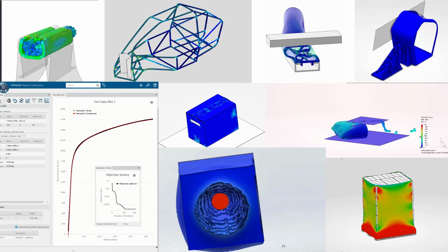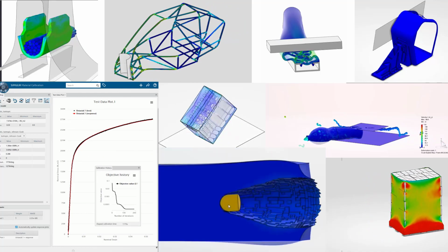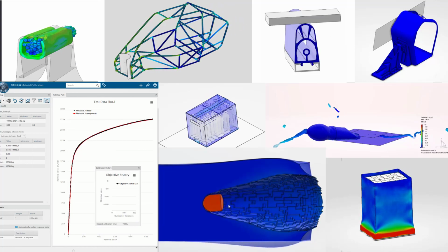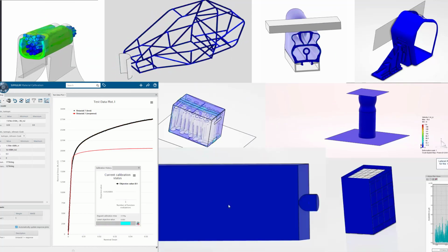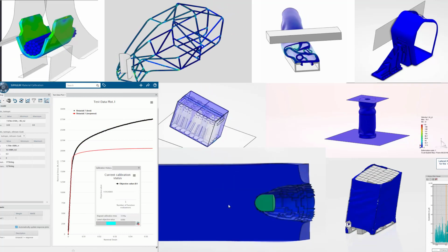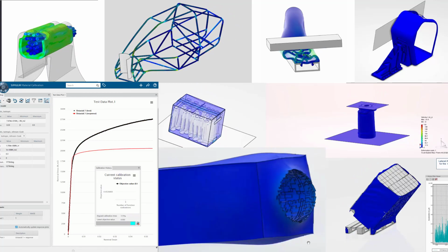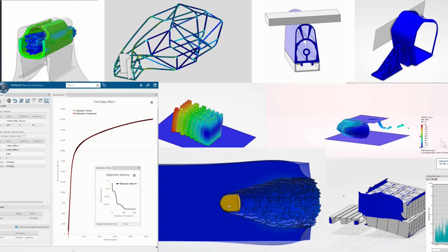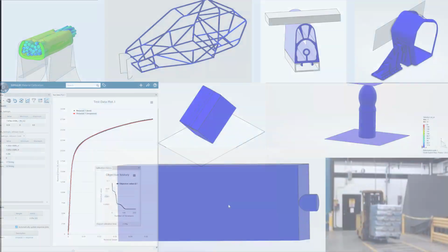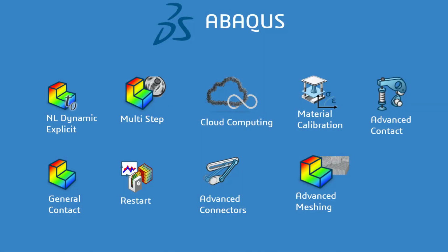Then the last example is preloading the shrink wrap around a pallet full of boxes. And then the next load is running that into a wall for a dynamic test. You can also see the fracture element here where that shrink wrap is actually ripping due to the strain being too high in that simulation. So again, another set of examples that kind of showcase where ABAQUS really shines, those more realistic, nonlinear, dynamic type applications.